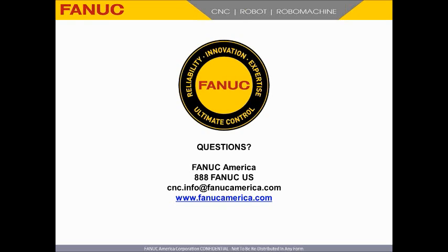Question here is, the probing routines, are they just calling Renishaw's 9,000 programs or FANUC-specific programs? No, they don't use the Renishaw stuff. It's macro variable programs that FANUC has done. It's actually resident in the machine itself. No, the Renishaw macros are not in there, no.